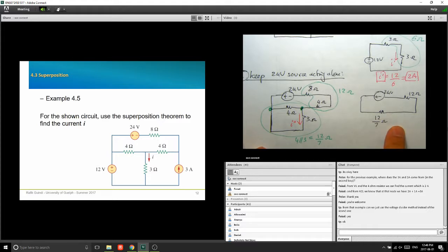Okay, but in this circuit, I don't see I naught double prime. Okay, that branch has vanished. So I'm going to solve here to get this current. Call it Ix. You can call it anything, it's just a variable. Okay, now Ix equals, actually, sorry, not that. I'm going to put it like this because of the plus and minus that I have here. Ix is 24 divided by 12 plus 12 over 7.